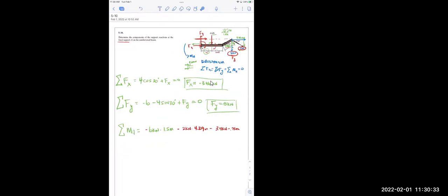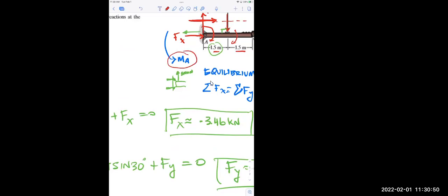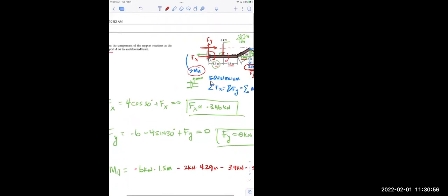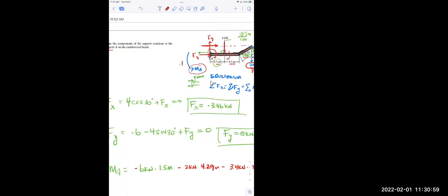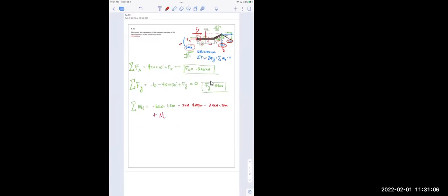So basically all 3 of those components want this thing to rotate counterclockwise. You can probably appreciate that if that was not a fixed support, if it did not have the ability to resist that, then this thing falls over. That better be fixed supported, because that thing's rotating if it's not. Notice I drew this in coincidentally in the positive direction, counterclockwise. So down here, I would be adding that and saying plus the moment around A provided by that fixed support. And so I got to solve that. Again, all 3 of these equations had just one unknown in them, so I could have solved any of them anytime I wanted to.